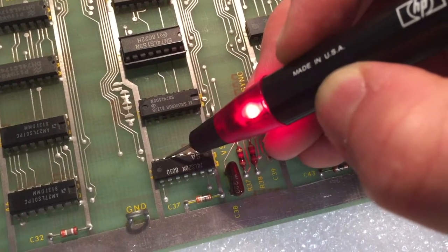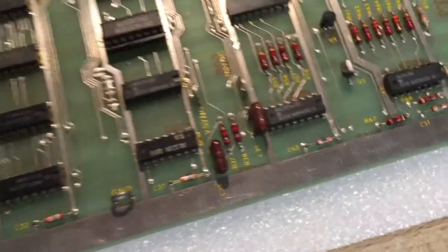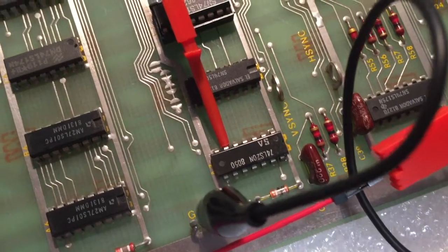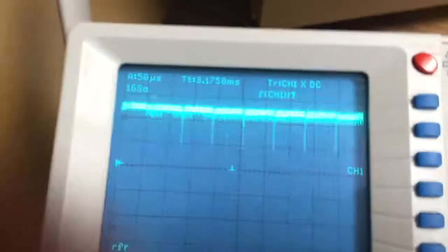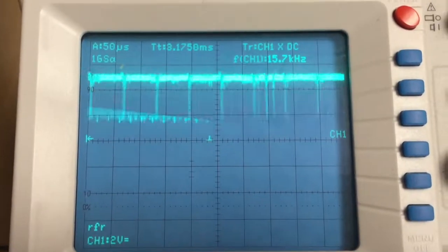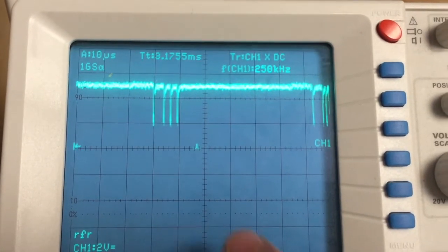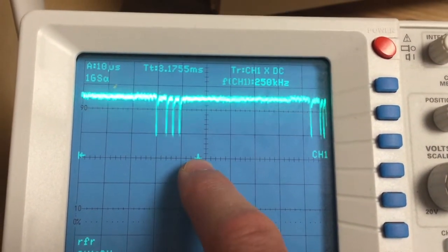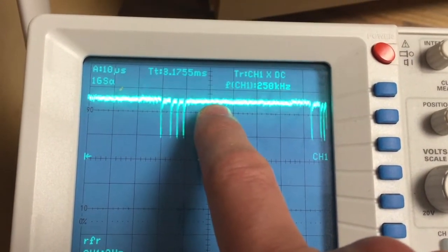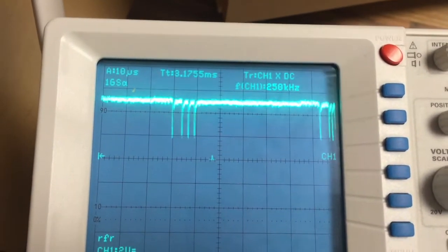I found another interesting clue when I looked at the signal with my oscilloscope, which I can show you. Okay, so I hooked the signal up to my scope, and you can see the result here. Let me just stop this signal for you. Okay, so this is the baseline, so this is 0 volts, and up here we have 5 volts, which would be a high signal.